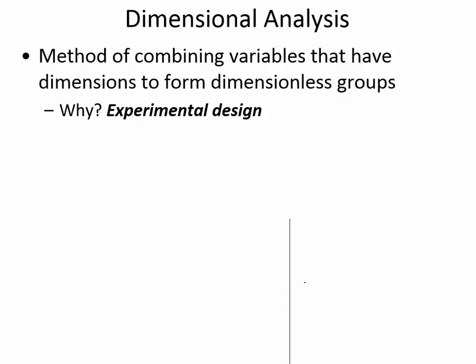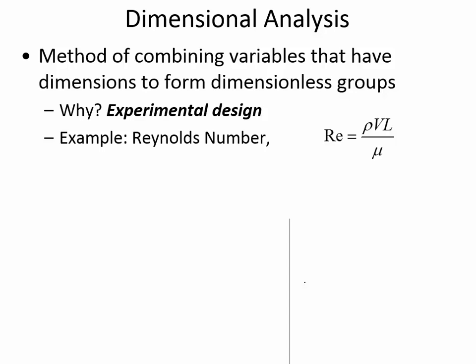So let me tell you about dimensional analysis. There's a process called pi groups. Generating a pi group gives you a unitless parameter. If there's a whole list of variables that are somehow related to predicting a parameter, like what the drag force will be, then you can rearrange the variables to try and find what the equation is according to developing pi groups. A pi group is a unitless parameter. Just take Reynolds number, for example. We've just been calculating Reynolds number here with dynamic similitude. Reynolds number is a unitless quantity.